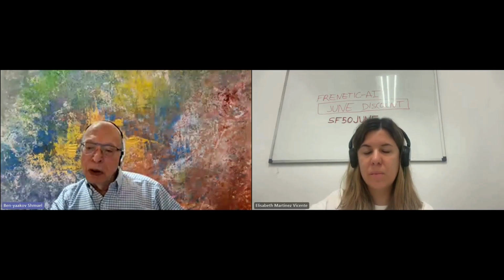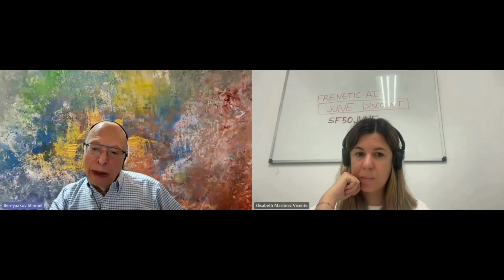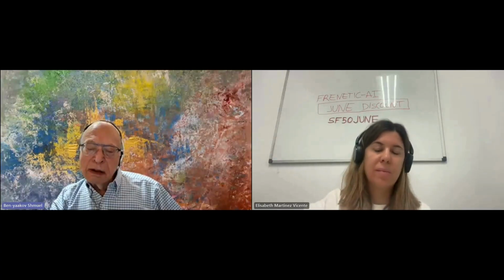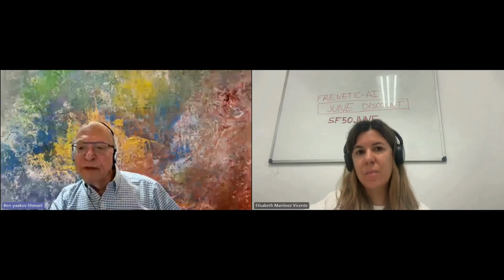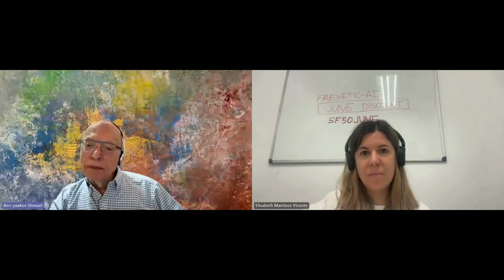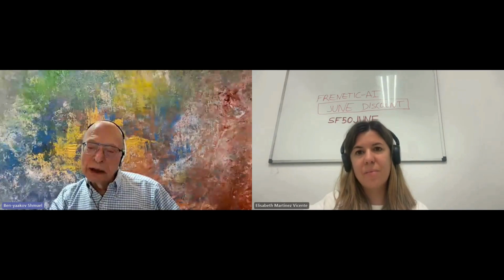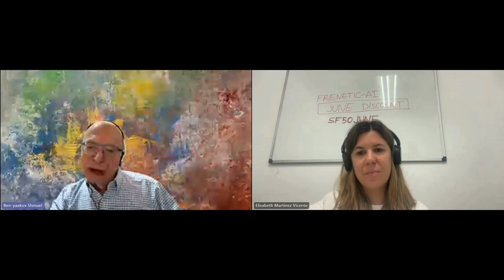Look at it as a black box with some parameters, input and output, like a two-port network. This can be modeled by many equivalent circuits, and you can have many equivalent circuits which will have a different value of leakage, a different value of magnetization, all of which will provide you the same terminal behavior. That is, you can have the same behavior with different inside equivalent circuits. So it's not easy to answer the question.